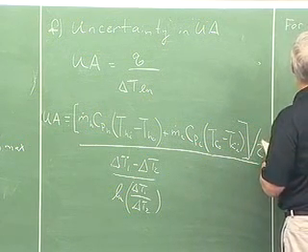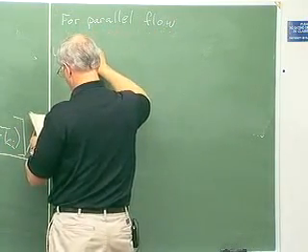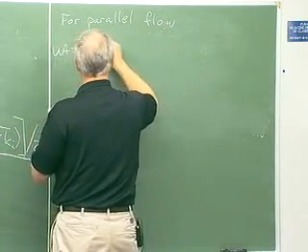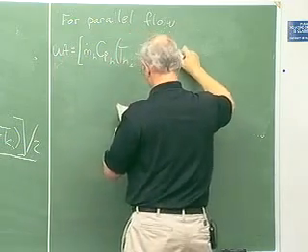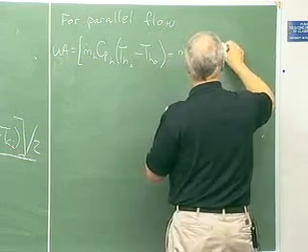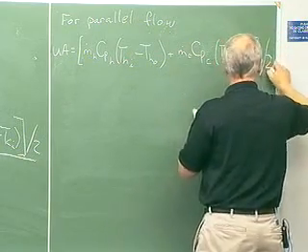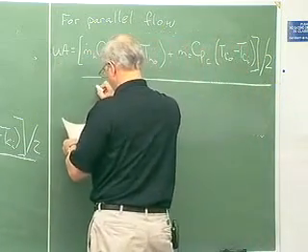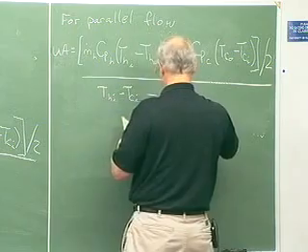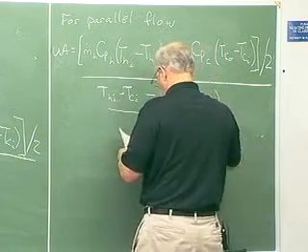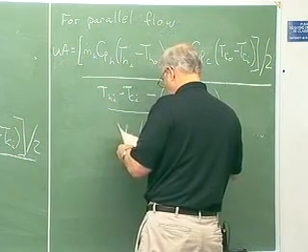All right, so for parallel flow, we have the UA equals m dot H Cph times T hot in minus T hot out plus m dot C Cpc times T cold out minus T cold in, all divided by 2, divided by, so delta T1 is T hot in minus T cold in minus T hot out minus T cold out, all divided by the log of T hot in minus T cold in over T hot out minus T cold out.